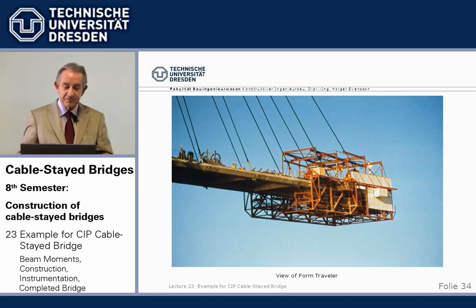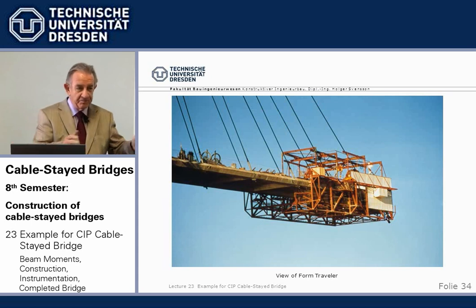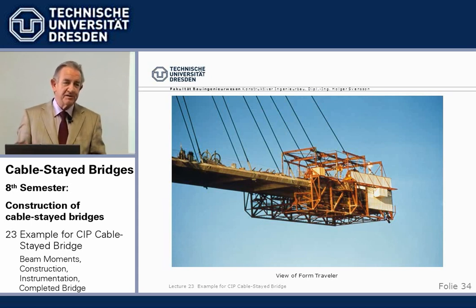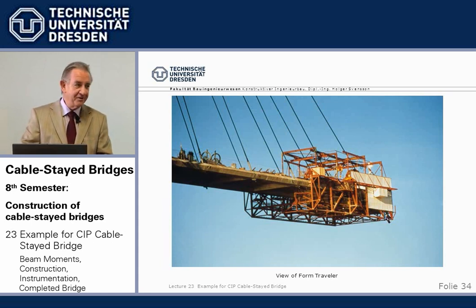We said, okay, we use some, I call it, flimsy plastic sheets. So when the high, difficult wind comes, it's blown away by the wind. So when we have the governing wind, that thing is gone. So that was a solution: under regular conditions we have the people and the concrete protected. And under high storms, when we have the governing loading, bending transfers on the beam, Kovacs was satisfied it will not be there. So you have to think up solutions sometimes if you go to the limit.